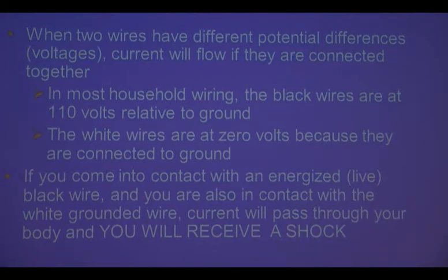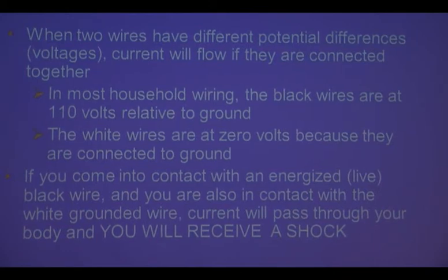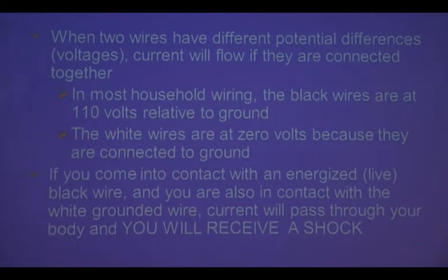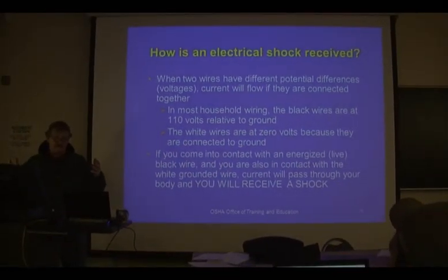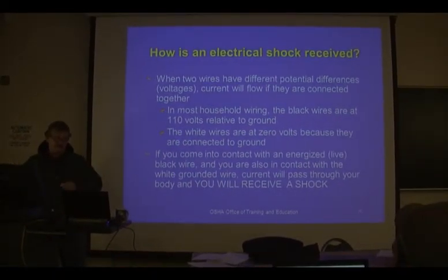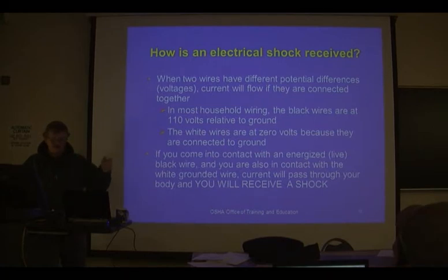You're switching the ground, aren't you? Aren't you still having voltage flow? I mean current flow, I mean? You're still having current flow, right? So there's no problem. The equipment will still work. Right, but your white one's hot, so if somebody else comes up, grabs onto it thinking it's neutral, it's hot.